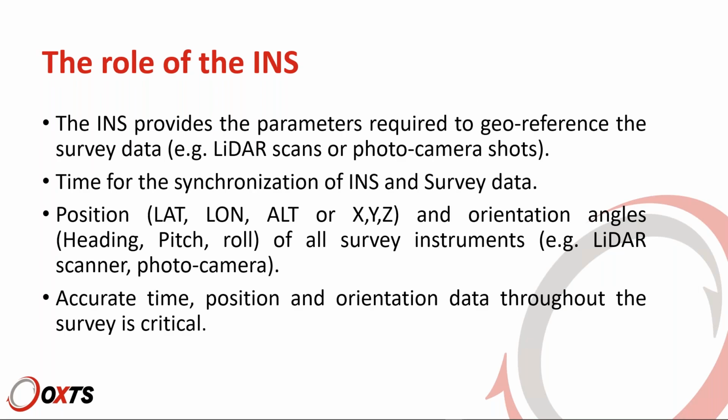The INS provides all the parameters that are required to georeference your survey data, camera shots, LiDAR scans, and so on. Time, first of all, so we can sync all the data to the INS data. That's the GPS time that the INS will use. Position, obviously, either in absolute lat lon alt coordinates or in XYZ local coordinates if you have set a local coordinate system.